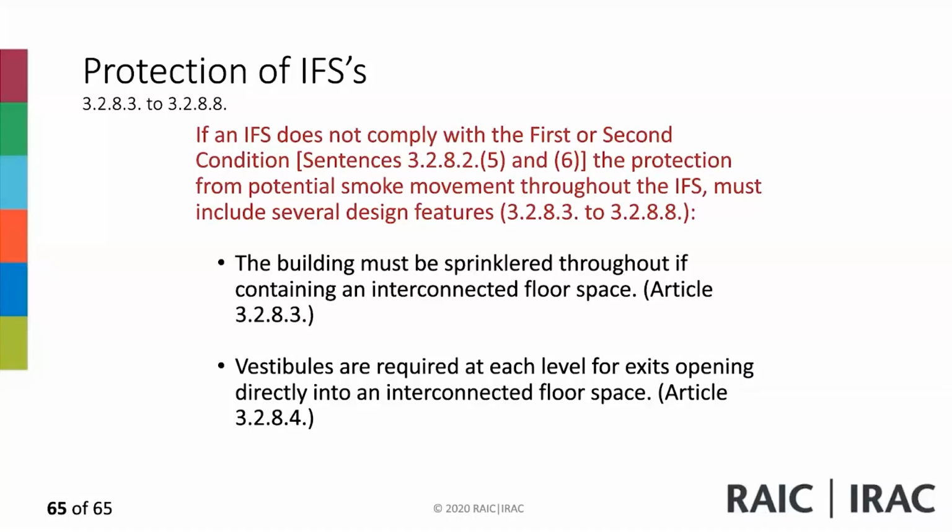3.2.8.3. So 3.2.8.3 is pretty clear. The building must be sprinkled throughout. Now 3.2.8.4, vestibules are required at each level for exits opening directly into interconnected floor space. So you have to provide for vestibules.